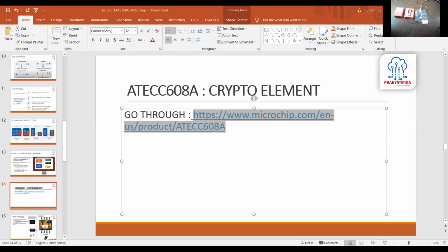So there are two versions of it. The ATECC608A is still in production, but not suitable for newer designs, because newer designs generally have LoRa based communication now. So 608A or 608B, everything is the same, only the 608B has the special LoRa communication security features.